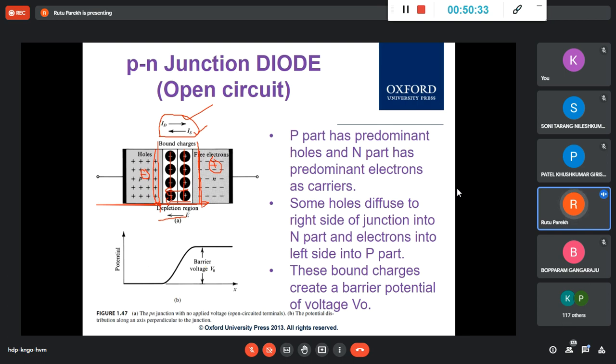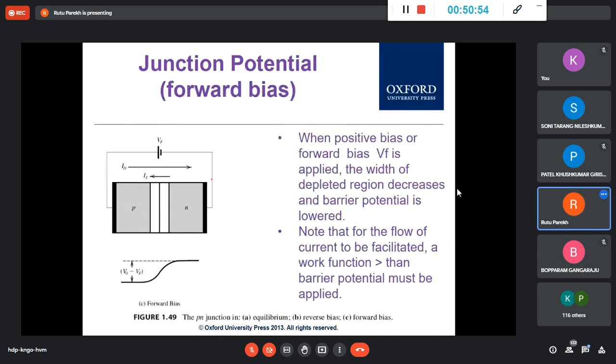And if this gets thinner, then from 20 it becomes 10. So it gets thinner, and the electric field, the potential that it has... you have studied that if we give 0.4 or 0.5 volts, then it will conduct at 0.7. So 0.7 is enough energy in forward bias that the barrier has gone very thin and it is easy to cross, and you will have huge current when it is 0.7. At 0.3 or 0.2, the wall is still thick enough that it will be hard for the electrons to cross.